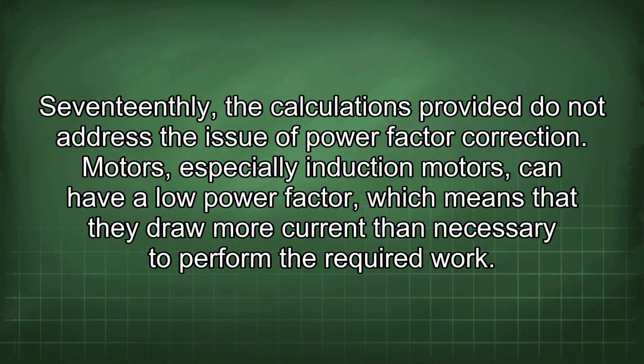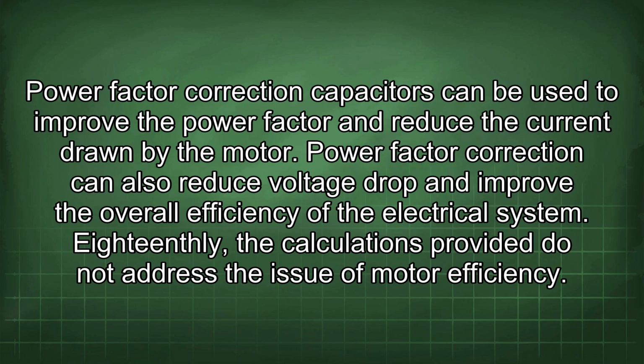17thly, the calculations provided do not address the issue of power factor correction. Motors, especially induction motors, can have a low power factor, which means that they draw more current than necessary to perform the required work. Power factor correction capacitors can be used to improve the power factor and reduce the current drawn by the motor. Power factor correction can also reduce voltage drop and improve the overall efficiency of the electrical system.